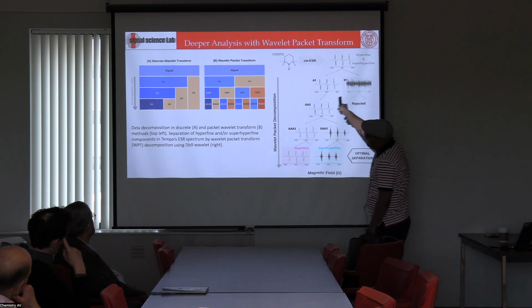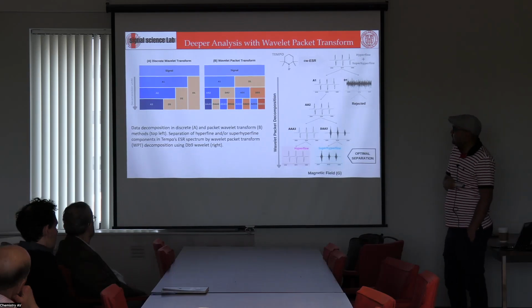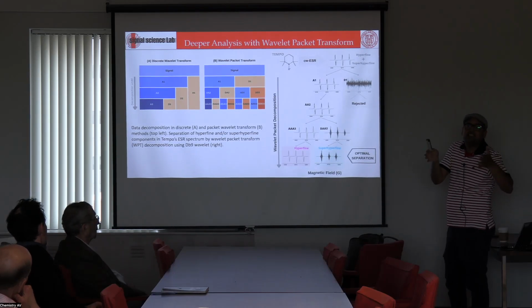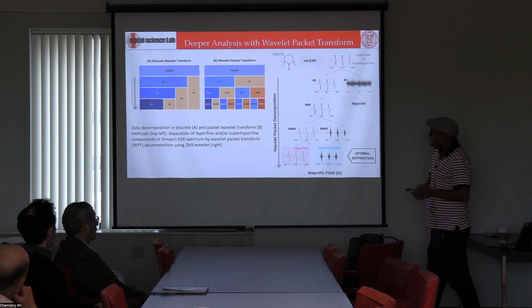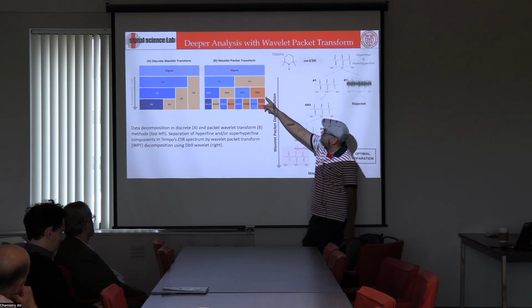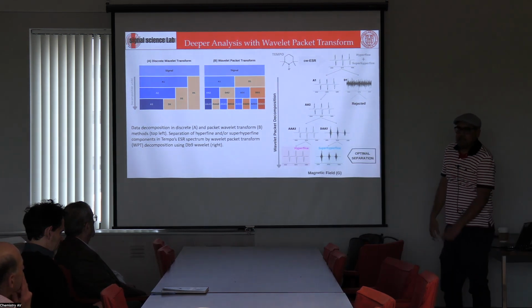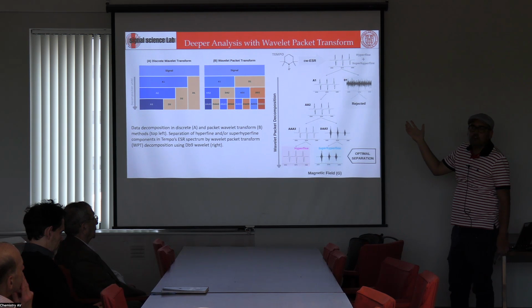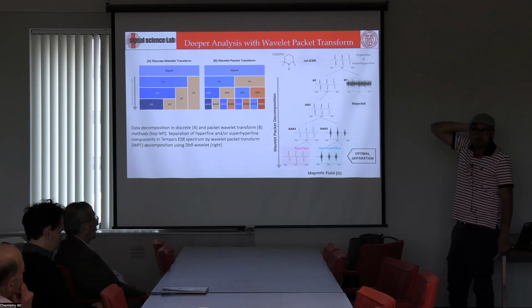The difference between the wavelet packet transform and the discrete wavelet transform that Daubechies developed is that it preserves the data length. That comes at the cost of resolution in the discrete transform. If you're preserving the data length of input and output data, this does not come at the cost of resolution. It is actually the best way to get resolution. But you get so many components that your data storage becomes big. That's why wavelet transform has not been applied to, say, cryo-EM with so much enthusiasm, because when gigabytes of data can generate 50 GB of wavelet components, good luck processing that.